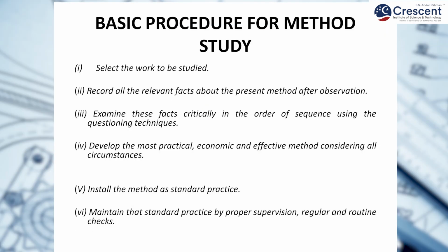Let us consider the basic procedure of method study. The prime step towards method study is selection of the job, that is, which type of job we will select. In the next slide I will tell you the criteria for selection of a job. Next, we will record all the relevant information and facts about the job method, then examine it critically, and after critical examination we will try to develop a new or better method.